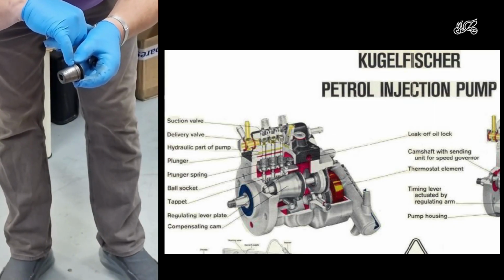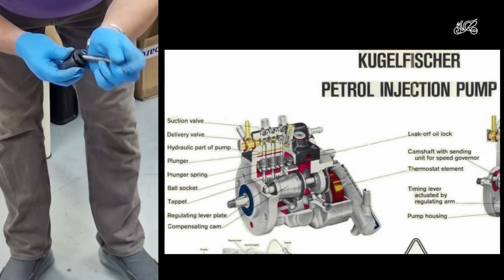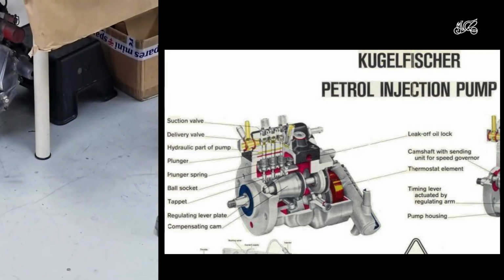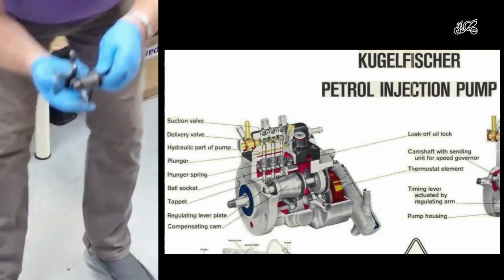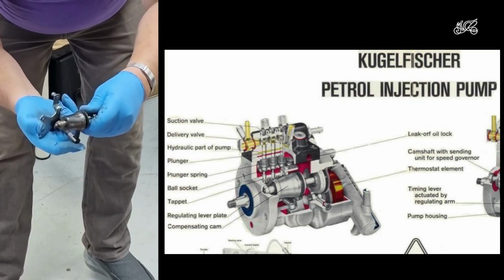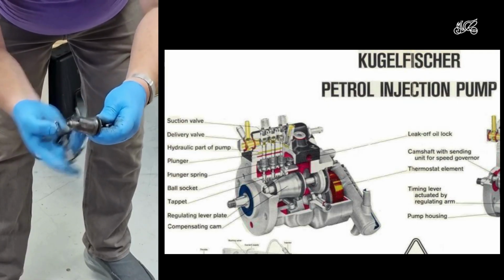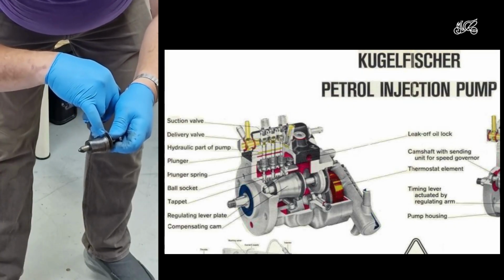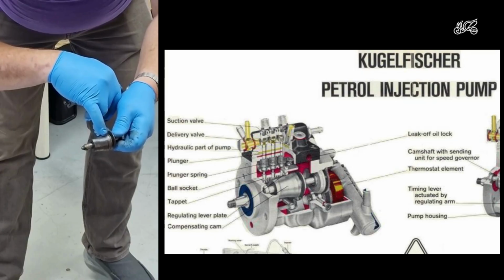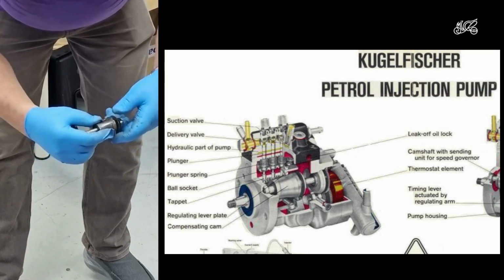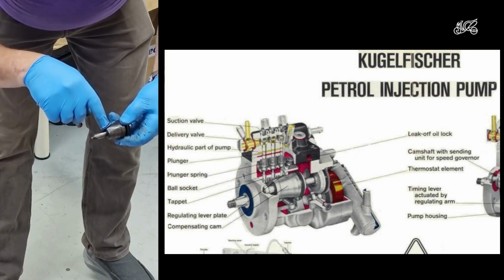When this sits on this shaft with this lever underneath, and when I press the throttle, I pull this piston back. So the little nub on that plate you saw earlier goes from sitting on this high point to sitting down here because this moves, yeah, and so it delivers more fuel.